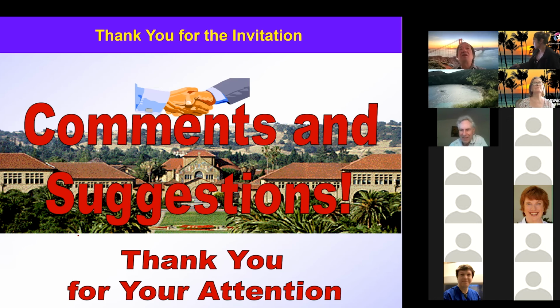Right now, the typical inspection cycle is about 2 years. Even though 2 years is perfectly okay, you might need it earlier, or you might be able to extend it a little later. So in a data-driven way, if you run the sensors for a little bit longer and have enough confidence, then maybe you can extend it, for a newer bridge, to maybe 3 years.